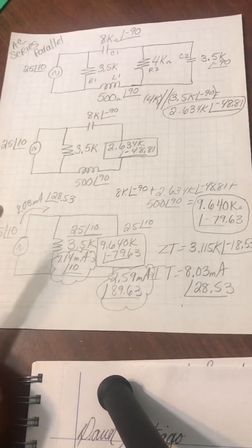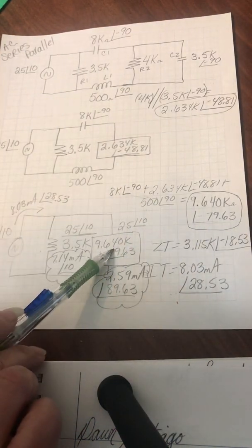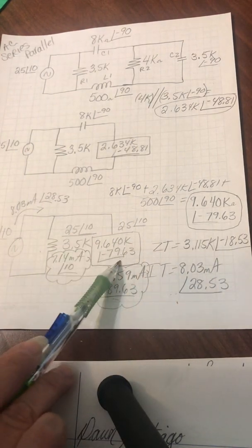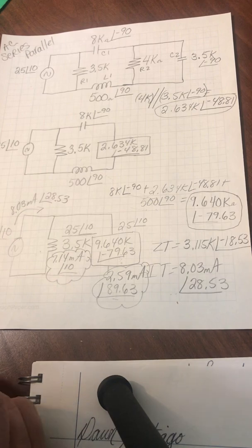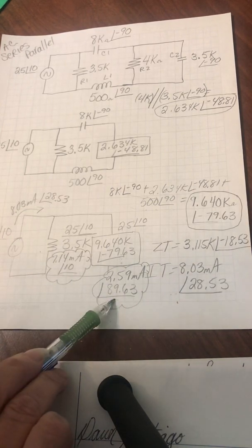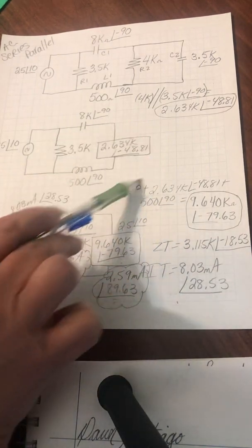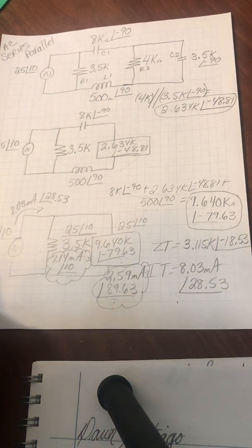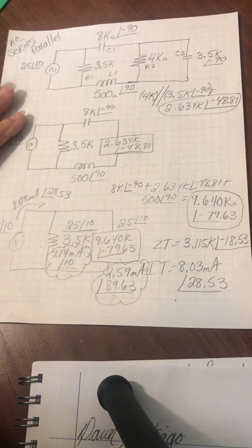So the reason why we note these things here and what we've done is because now we know this is the voltage across this. This is the current through this. How did we get this? We did the series combination. So what's constant in a series circuit? Current. So this current is going to go back here, here, and here, which is right here. So these three will share the current. Then we have to get their individual voltages. And their individual voltages must add up to 25 at 10. So let's bring that.